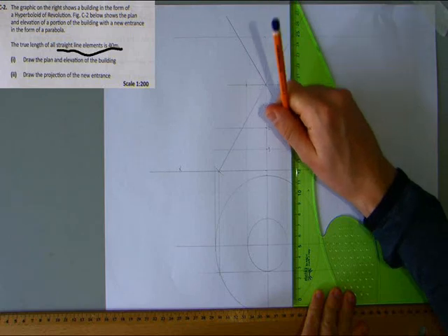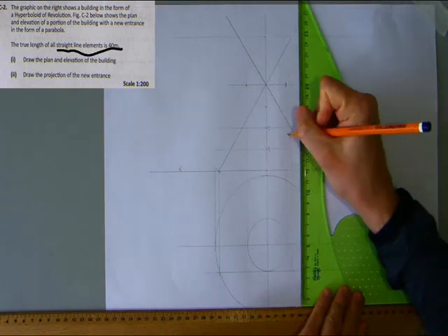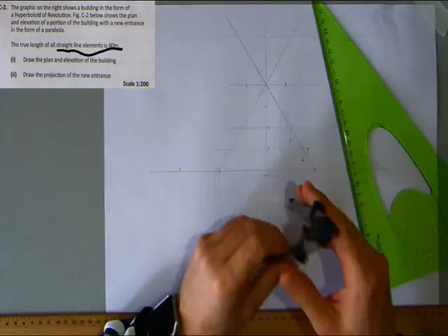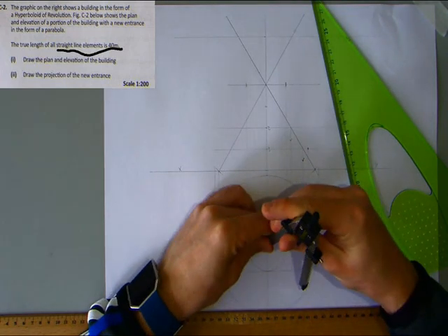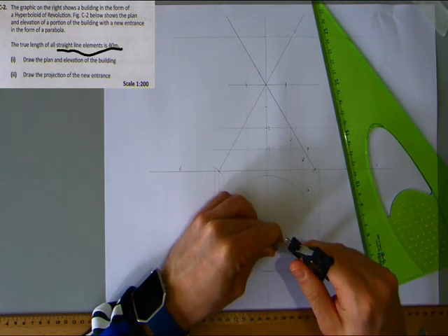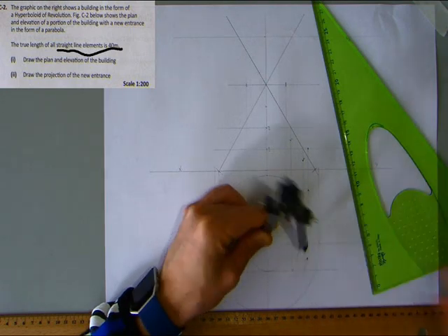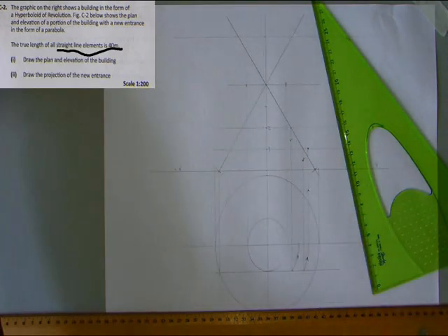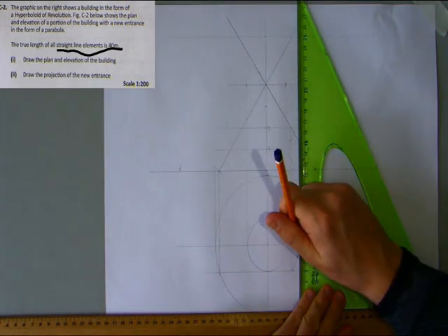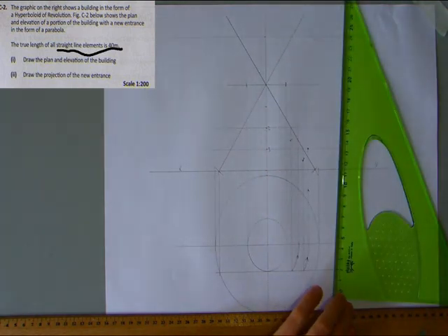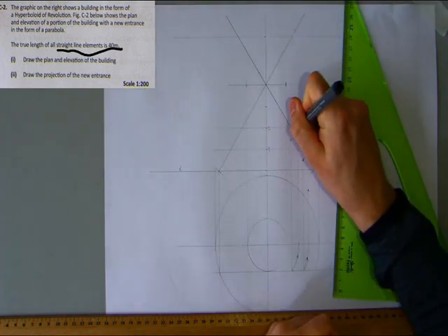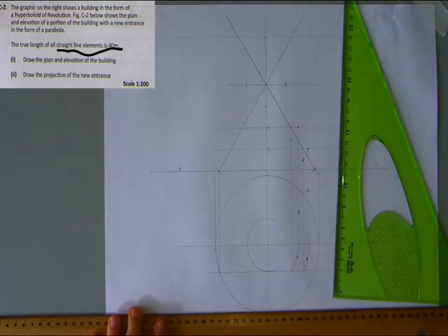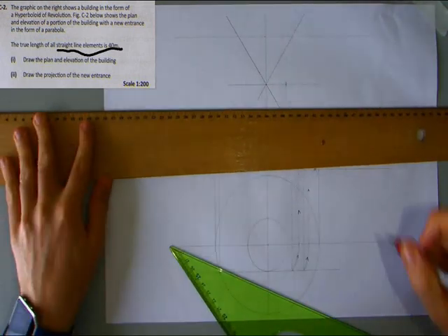We know our asymptote in plan, so we can bring that down to our asymptote in plan. We can then take that radius from the central axis of the hyperboloid of revolution, and we can now swing it around to our extreme generator. And from our extreme generator, we can bring that back up to the corresponding height. Again, giving us another location on our hyperbola. Again, creating cut number 3.